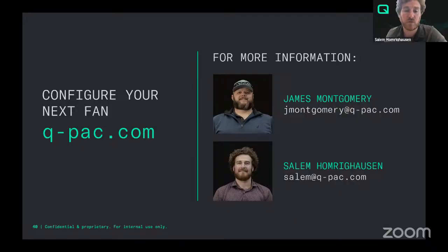When we designed the control panel, we tried to mimic a VFD, since it looks like a VFD when it's mounted on the wall. But the actual speed modulation and power inversion, when it converts from AC to DC to actually control these things, is in the back of the ECM motor. So that's that. But currently you can't control with a combination of those things, as far as I know.